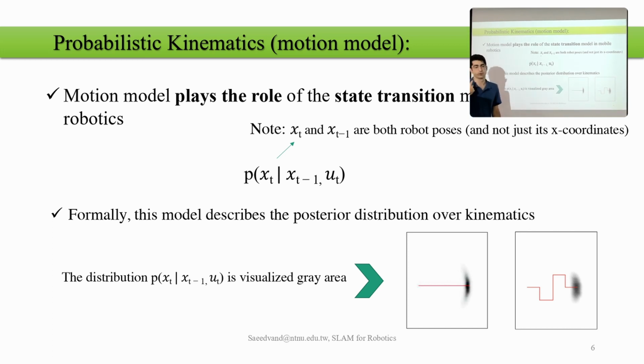I want to clarify, when we are talking about localization, when I'm moving from there to here, I'm going to predict the probability of where the robot is, because I cannot say the exact xy. I want to say somewhere around this circle, and this can be a distribution like these shapes here. That says the robot is more likely here, but maybe here, maybe here, less likely here in this distribution. But if it was Gaussian, then everywhere in one circle on the xy would have the same probability.